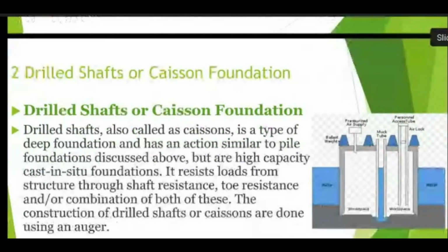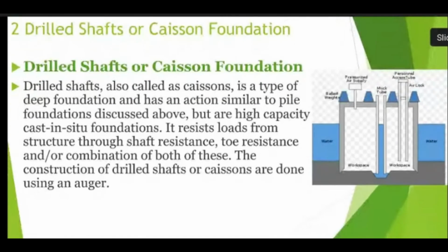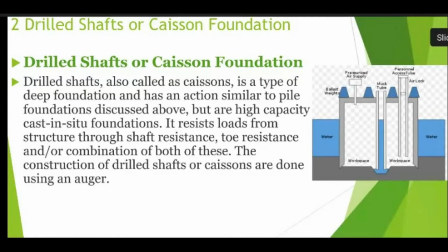Second, drilled shafts or caisson foundation. Drilled shafts, also called caissons, are a type of deep foundation and have an action similar to pile foundation discussed above, but are high capacity cast in situ foundations. It resists loads from structure through shaft resistance, toe resistance, or a combination of both of these. The construction of drilled shafts or caissons is done using an